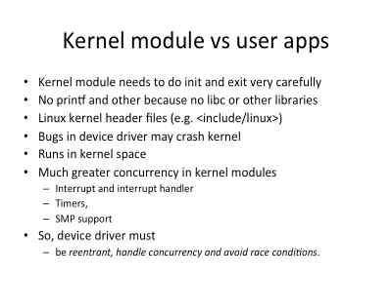For example, if you have a FIFO buffer maintained in your device driver, you have producers to the buffer, you have consumers of the buffer, and you may have multiple producers and multiple consumers. You have to deal with how you move the pointers to track the available bytes in the buffer. That's going to be challenging.